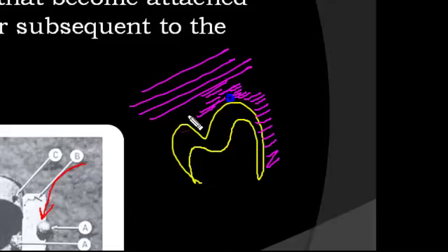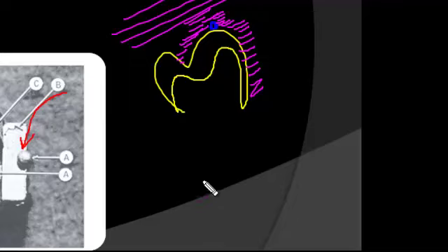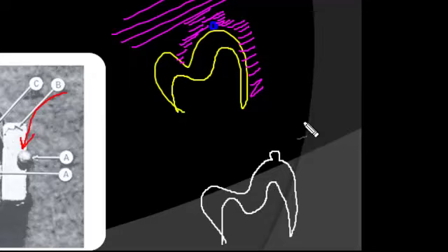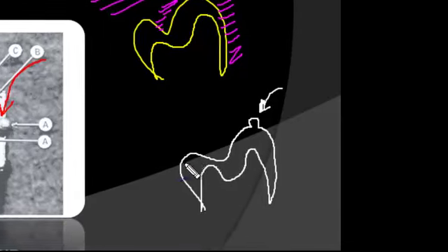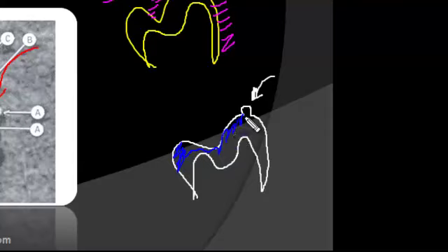Now when the wax is burnt out, we will obviously get a mold cavity that will have this kind of configuration because of that particular air bubble that created the shape. In this kind of mold cavity, when we put the metal, the metal flows into this space created by the air bubble, and once we get the casting, it will have a nodule on it.